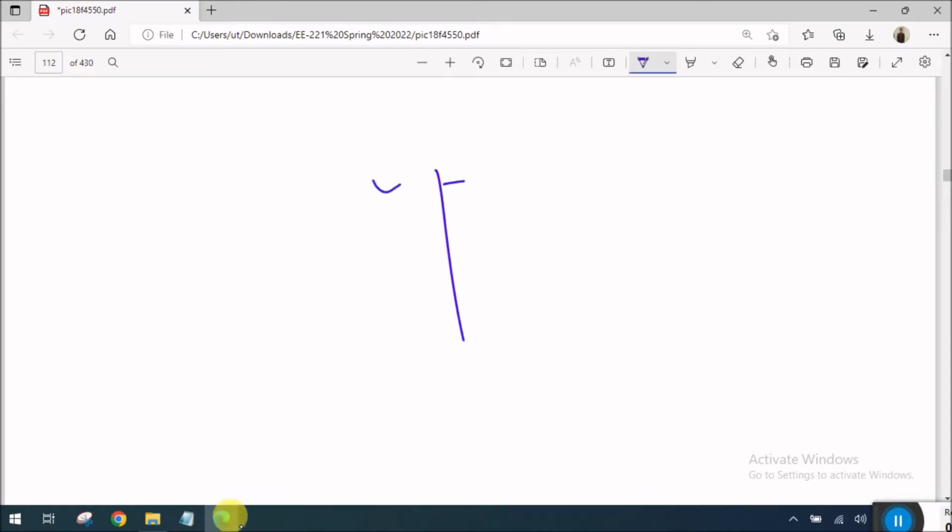So I can send any signal to this pin that can be a 1 or a 0, and I can drive my load, which can be an LED or a motor or anything, with this signal. So let's just draw an LED again. Here we have our load connected to this pin. And my program is just sending some ones and zeros alternatively to this pin to toggle the state of the LED to let it blink.